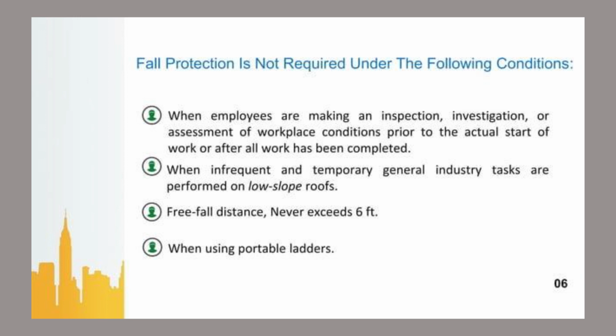Fall protection is not required under the following conditions: when employees are making an inspection, investigation or assessment of workplace conditions prior to the actual start of work or after all work has been completed. When infrequent and temporary general industry tasks are performed on low slope roofs. When free fall distance never exceeds 6 feet when using portable ladders.